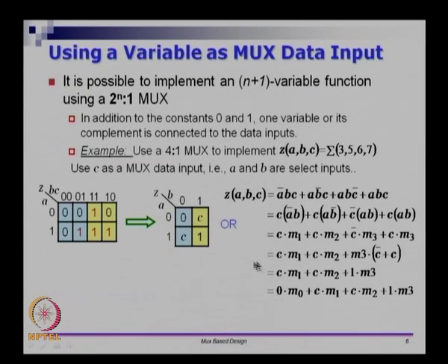So you can do this, or you could have done something slightly more elaborate. I did it directly in the map here. You can also do this from basic Boolean functions. So you go and look at this. We have A bar BC plus AB bar C plus ABC bar plus ABC. These are the terms 3, 5, 6 and 7 respectively. In each one of them, remember, because it is a minterm, they are all in normal form. So you can take C out, you then see A bar B, AB bar, AB, and so this is AB bar, which is 1 0, then you have AB and AB. So this is from 6 and this is from 7.